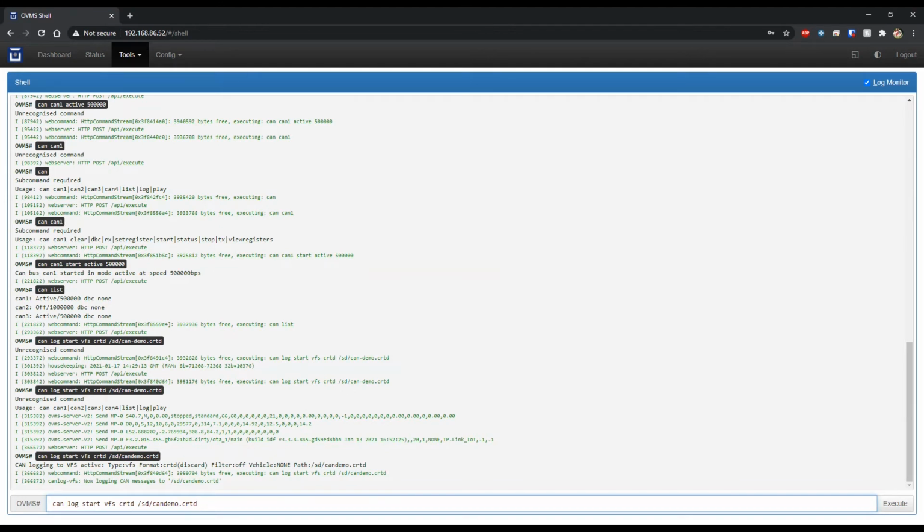So our next step will then be to send the command. Now the command we need to do is CAN1, as we're sending it to the first CAN network. Transmit is TX standard. So this is a standard frame. And then the address is 0x7df, as we discussed before.